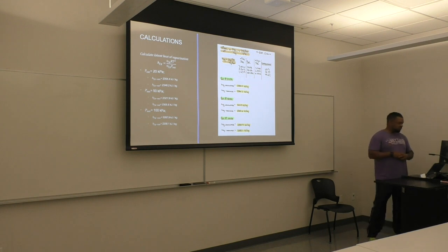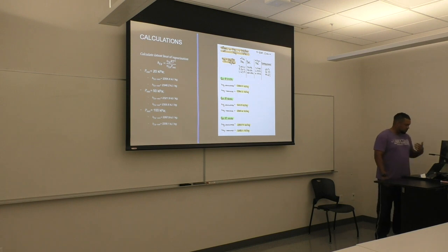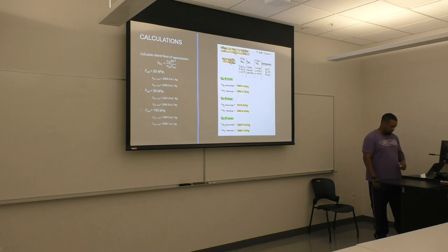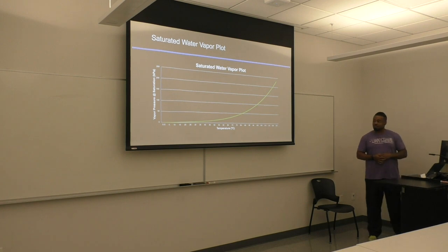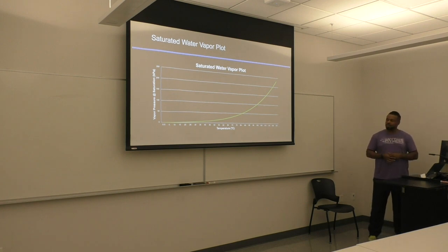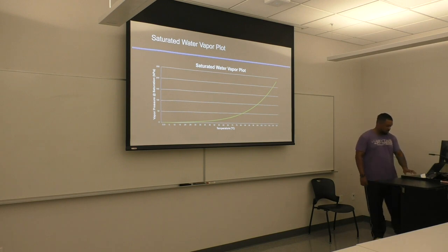So as mentioned before, we have the Clapeyron equation. It can be manipulated to get your latent heat of vaporization. I took 3 different saturation pressures of 20, 50 kPa and 100 kPa. Here are my results over here on the side. Actually, all 3 calculated values were slightly higher than the tabulated value. Also, in the steam tables in the thermodynamics book, here's a graph that was created from those values.